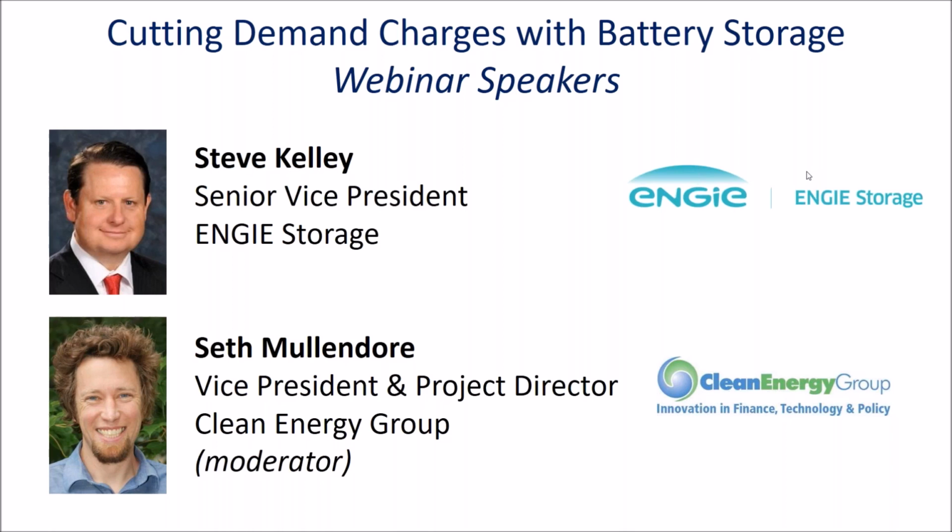You're looking at fire suppression that needs to be built in. You're looking at a number of different things that they're adding into the code, which makes the cost to install them almost 2 to 3x. And typically when you add 2 to 3x to the installation cost, which currently right now is about, on a 250-500, about 20% of the total project cost, it does hurt the economics significantly in many of those situations.